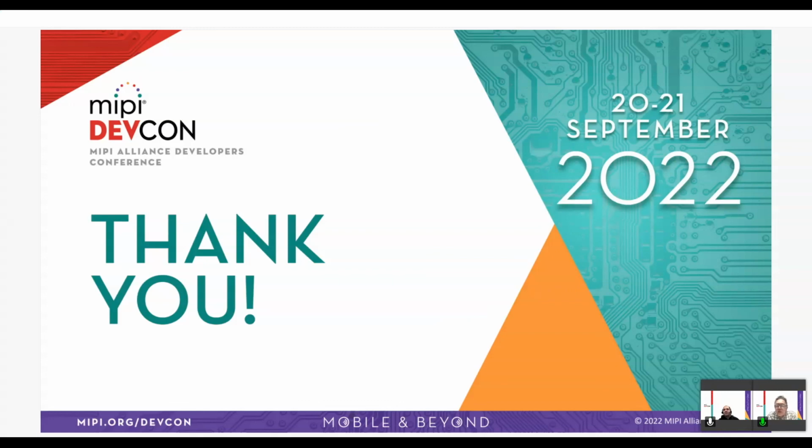Okay, and do you know if there's any plans to? You mentioned that you have integrated the D-PHY. Are you seeing anything moving up to the D-PHY 2.0 or the C-PHY 2.0 being integrated or higher? As earlier we had the PHY roadmap going up to 3.0 right now in the specs. So where do you see that going? If this question is about a MIPI bridging solution, the one we are discussing today, or in general, I would say the answer to both is yes. We see newer D-PHYs and also C-PHYs deployed in those MIPI FPGA-based bridging solutions. And in general, we see high demand on newer versions of MIPI D-PHYs and C-PHY supporting much higher speeds, like 6 gigabit per second D-PHY mode, and similarly in C-PHY mode, but gigasymbol per second. Okay, that's great.